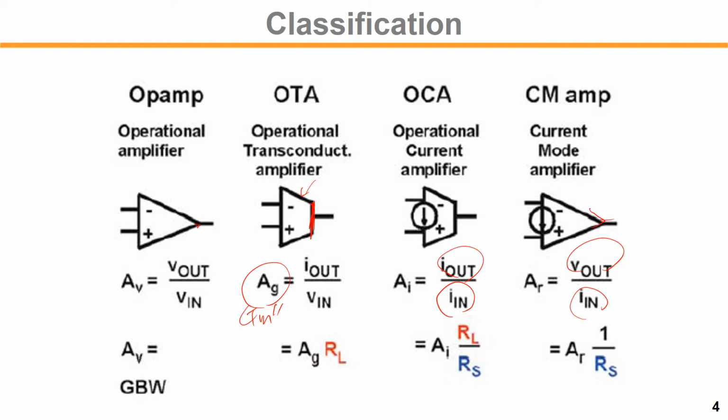For each case, we can define the voltage gain from input to output. For the amplifier, it has the inherent voltage gain, just as it is given. For the OTA, we can only calculate the voltage gain for given RL cases. Once the RL is given, we can find the gain Gm times RL, right?